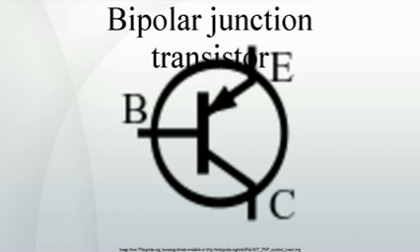In the NPN transistor in what is called active mode, the base-emitter voltage and collector-base voltage are positive, forward biasing the emitter-base junction and reverse biasing the collector-base junction. In the active mode of operation, electrons are injected from the forward-biased N-type emitter region into the P-type base, where they diffuse as minority carriers to the reverse-biased N-type collector and are swept away by the electric field in the reverse-biased collector-base junction. For a figure describing forward and reverse bias, see semiconductor diodes.